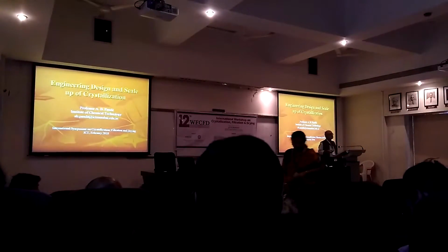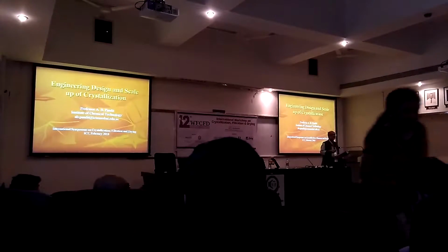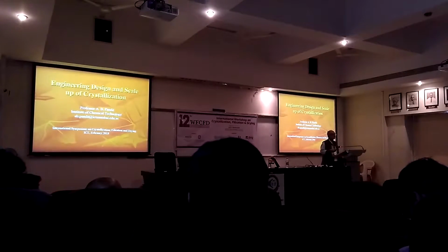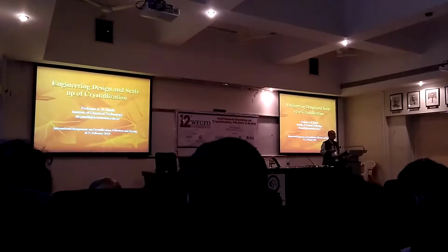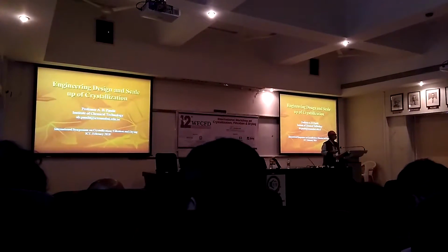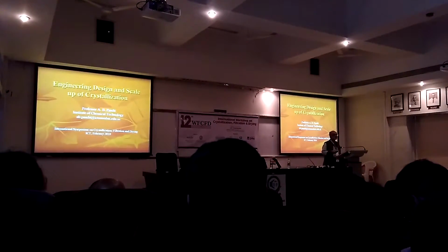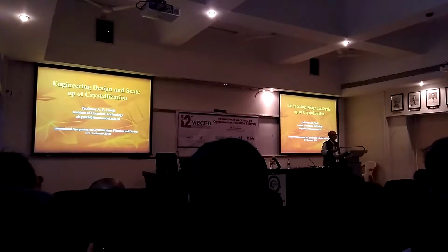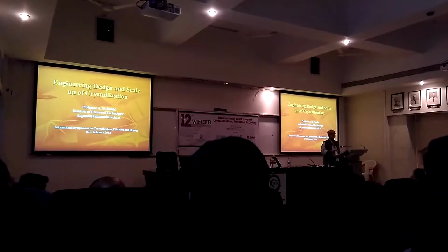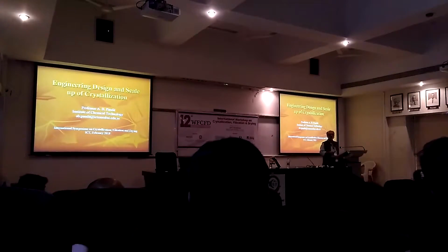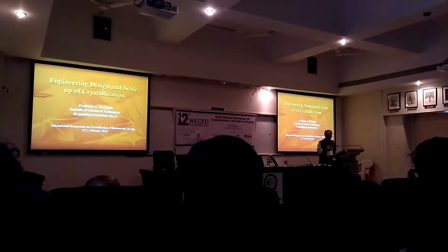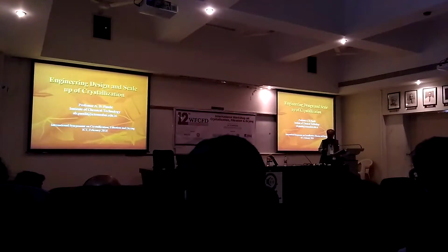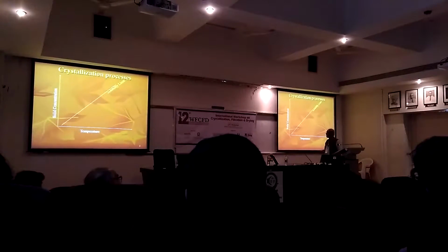So basically, any crystallization process, as you would understand, Mike has elaborated the role of the metastable zone and how to be able to get a controlled size distribution of crystals, how one needs to operate within the realm of the metastable region so that you do not get uncontrolled nucleation and you are in a position to control the crystal size distribution, which ultimately is a desirable property for the product which you are trying to make.